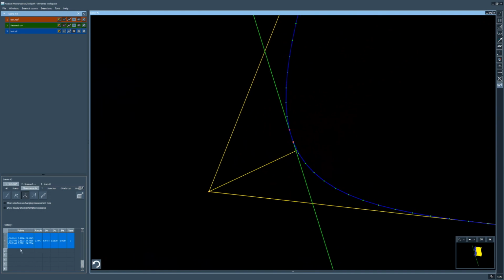And the result of that line is written down here. So the distance between those 2 points from our toolpath and the MPF interpolation point is 0.1447 millimeters. It's here in the results column.